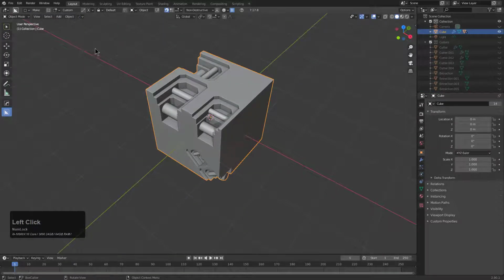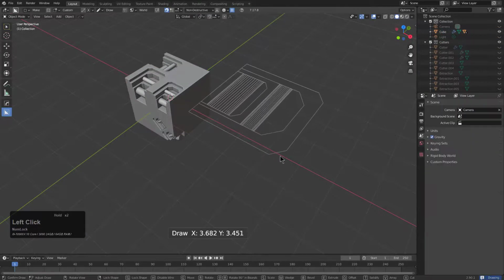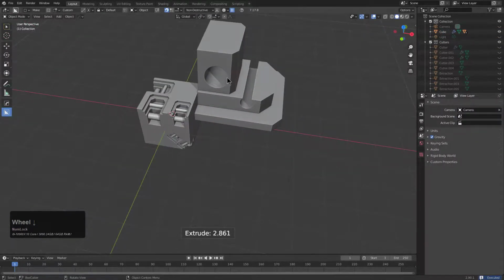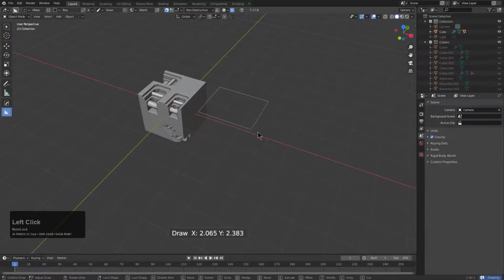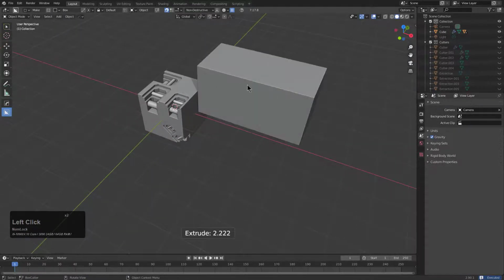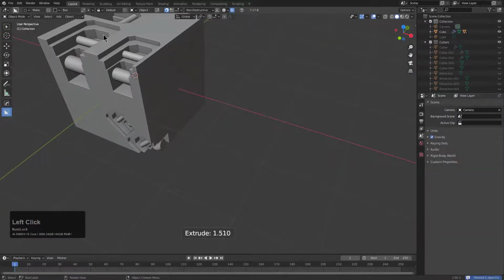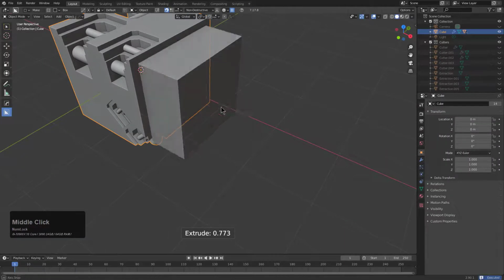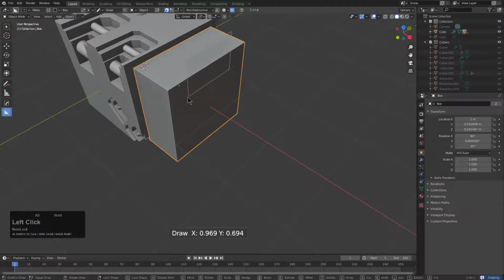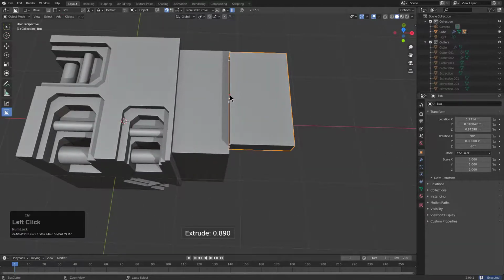Make is generally summoned whenever you have nothing selected. Like if I deselected this box and just drew, I would just draw a make box. However, not a custom. We want to switch this back over to box, and we could just draw out any shape we want without it being attached to anything via a boolean. And because we're in the make mode, that means that we can select this shape and just begin drawing make boxes using areas to jump off of, holding shift, and really get some interesting results.